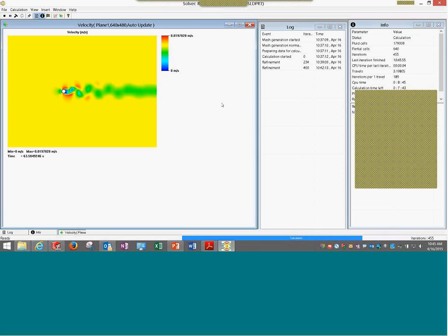In terms of the boundary layer, let's say the laminar flow layer, how many cells would you recommend to fill the thickness of the laminar layer? Typically they say 2 to 3 layers are required to be meshed along the laminar layer. I'm not sure about this software, but some tools talk a lot about laminar flow and give options to capture those flows accurately.